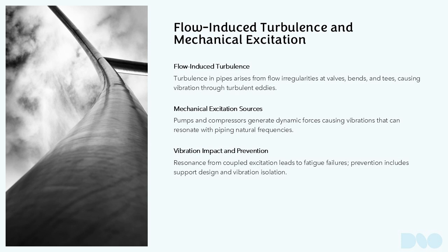When such coupling occurs, vibration levels can escalate dramatically, leading to fatigue failures at critical locations such as welds and small bore connections. Preventive measures include careful design of support arrangements, isolation of vibration sources, and operational adjustments to avoid coincident frequencies.